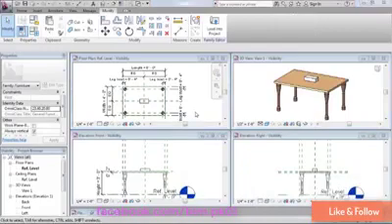An interesting property of all the solid forms in the family editor is the visible property. This property appears as a checkbox on the Properties palette, and it makes the selected element invisible. Now at first you may wonder, why would you bother to create a solid element only to hide it by unchecking the visible checkbox? Well, in most cases you wouldn't do this. However, like all the properties on the Properties palette, the visible property can be controlled parametrically. Now this opens up all sorts of useful possibilities. So in this movie we'll explore a really simple example of when you might want to use this powerful feature, and we'll see some other examples throughout the training series as well.